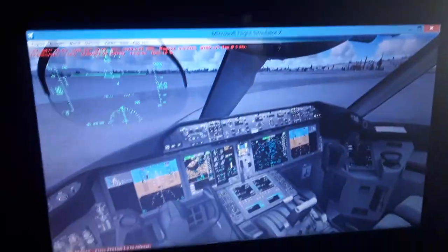We have also the LSZH localizer, the horizontal localizer and vertical glide slope. You can see the needles we can follow, using the transmitters which are positioned at the airport runways we use for takeoff and for landing. The transmitter frequency of the instrument landing system, the LSZH localizer. So we have the onboard antennas inside the aircraft that can receive this frequency and display the horizontal and vertical guidance for the runways we use for takeoff and for landing.